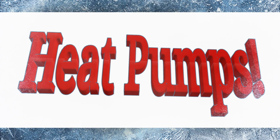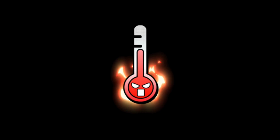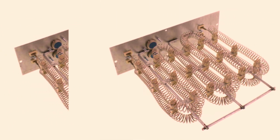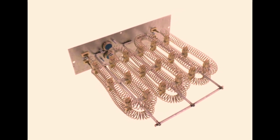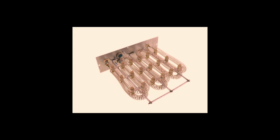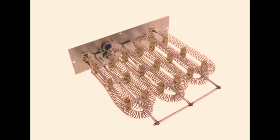Usually, heat pump systems will be a little bit more expensive up front to purchase. They're a little bit more complicated. They have a little bit more components. And if you live in a really cold climate, you may find a heat pump doesn't quite warm the air in your house as well. It may feel a little bit cooler. In those cases, if you live in a really cold climate and you want to use a heat pump, you also may need to have auxiliary heat strips or a second stage heating, where if the heat pump can't satisfy the thermostat setting for heating, then those heat strips will kick on to help satisfy the thermostat.